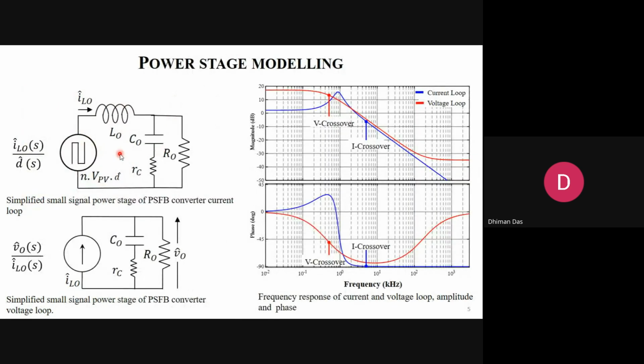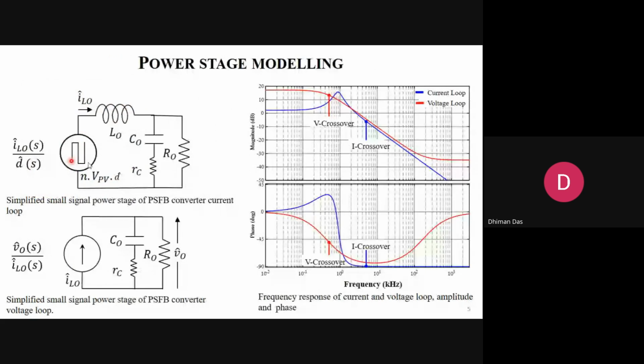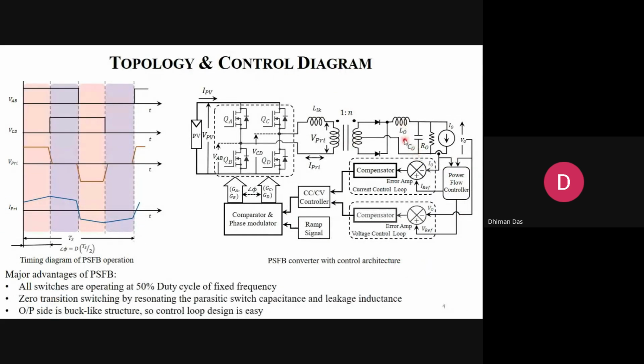Okay. So now the whole primary side, we can see this is a pulsating voltage here. We can model this as a pulsating voltage, and this is the output inductor, output capacitor, and load. So the whole converter now becomes just a square wave with double the switching frequency, because this is a diode rectification.